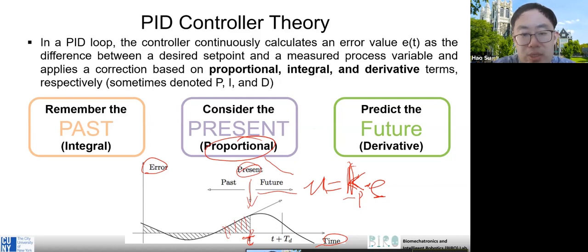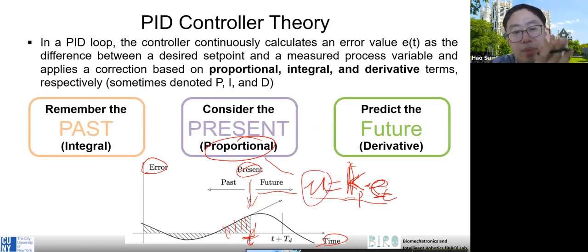So if we think about the proportional controller, this e is just e(t), the current error. This is the simplest controller that you can leverage to command the output. Can you think about why we also need the I, the integral term, and the D term?